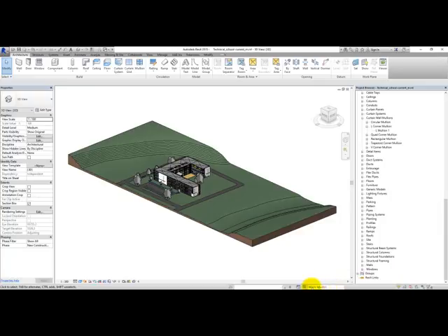Down here you see you've got what's used for design options. So the easiest way to explain that would be if you've got a room layout with some furniture in and the customer wants it in a certain way and you think you can do it in a better way, you can produce the same two layouts within the same model, and you can produce two drawings from them layouts all within the model. So you can basically set the view to that option A or option B. It's a really useful tool.